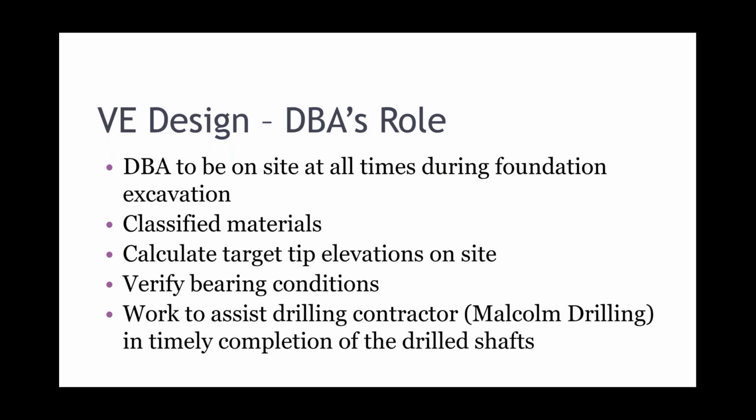So we're very big proponents of relying on both side and base resistance. Numerous load tests have demonstrated that both can be relied upon at compatible strains. But base resistance is highly dependent on the construction. So is side resistance to some extent, but for base resistance, particularly on large shafts where the magnitude is so ginormous, it's very important to make sure we have a clean base and it's verified. So we did that with airlift and the mini SID, which we'll get to a little bit later. And certainly schedule is king, as Van alluded to in his presentation. So we were working to help Malcolm get the drilled shafts installed as quick as we could.